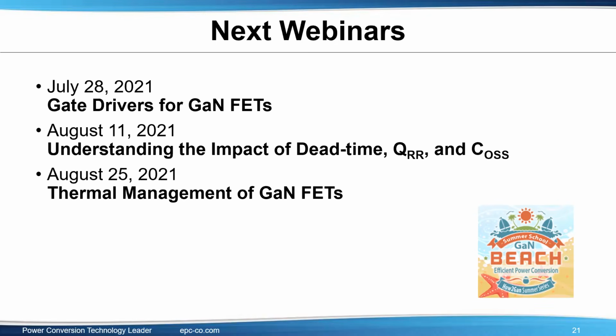What is the copper layer thickness for power and ground layer, and what is the formula for current calculation? Usually we suggest using a 2 ounce copper layer internally.